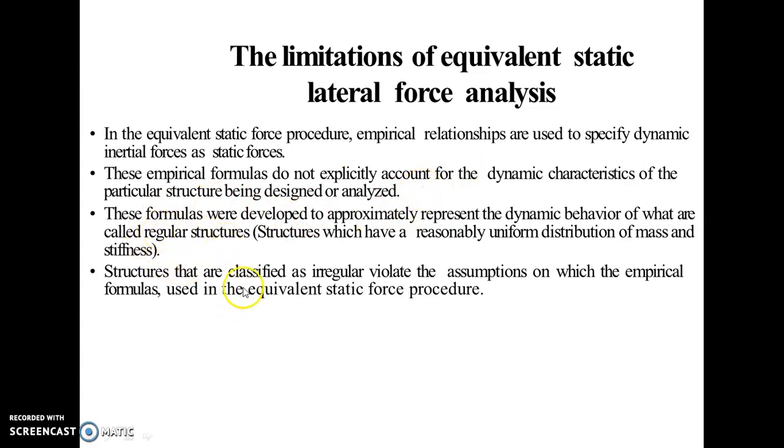These formulas were developed to approximately represent the dynamic behavior of what are called regular structures. A structure which has a reasonably uniform distribution of mass and stiffness is called a regular structure. And last, structures that are classified as irregular violate the assumptions on which the empirical formulas used in the equivalent static force procedure are based. Here irregular means there is a non-uniform distribution of mass and stiffness.